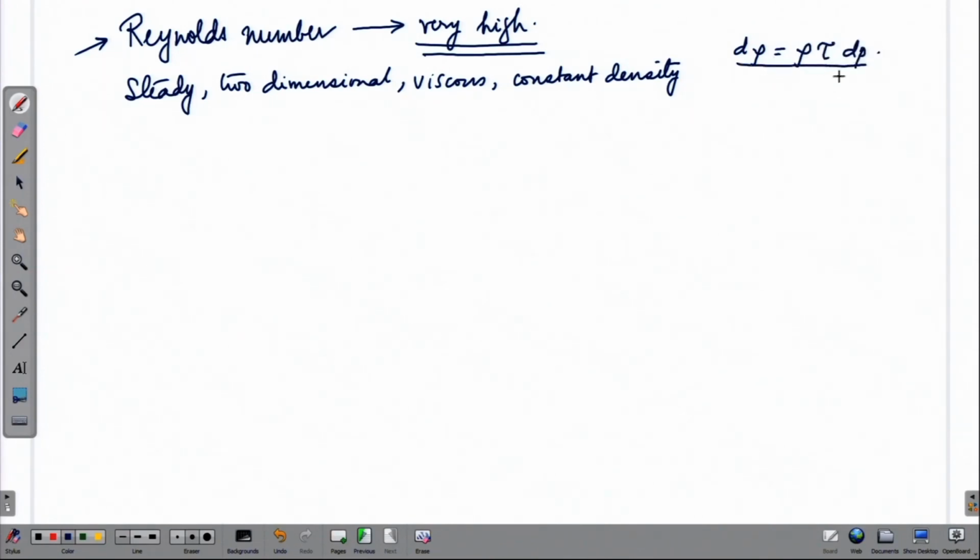we once again write down that relation which we mentioned in an earlier lecture. So, though the compressibility is high for gases, but if the pressure changes are nominal, then the density changes are negligible, and pressure changes are nominal for low speed flows. So, such flows can be treated as constant density or incompressible flows, that means as though the fluid medium is not showing any effect of compressibility.